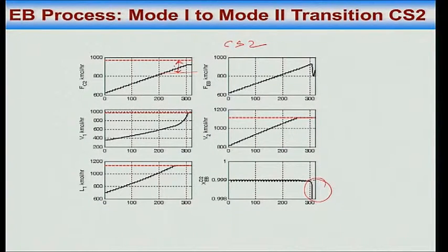Even though the plant is capable, your control system is basically screwed up. It's screwed up because you didn't take into consideration what constraints are going to become active and what am I going to lose because of that. It turns out here what I am losing is product purity control. Too much benzene contaminates my product. That's because V1 max becomes an active constraint. That's the problem. Yes or no? I think that's that. We'll finish it here.